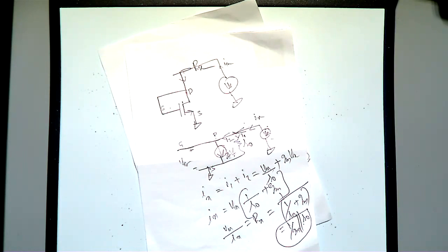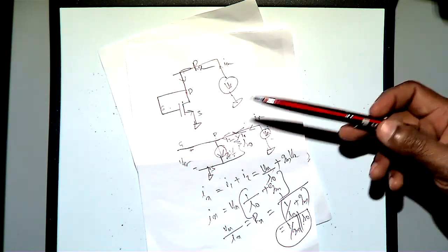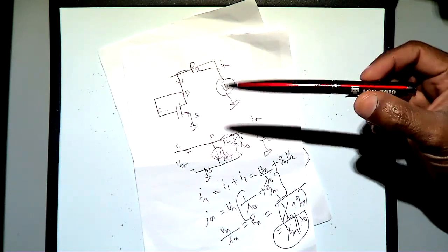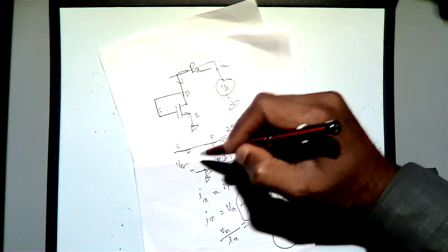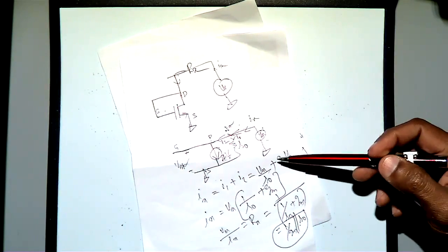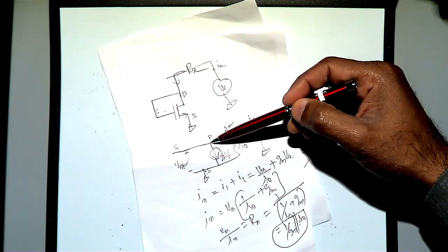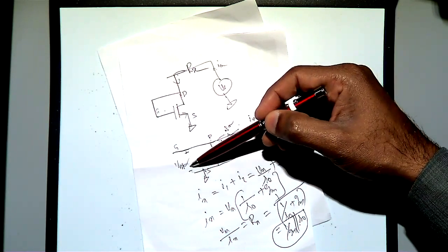See, that's quite simple. Because here it's very simple. So if you write down Ix, which is equal to Vx by Ro, because here the voltage is Vx. See, this voltage is Vx, this voltage is Vx, plus I1 is passing through to the ground, and here also this I2 cannot go through.